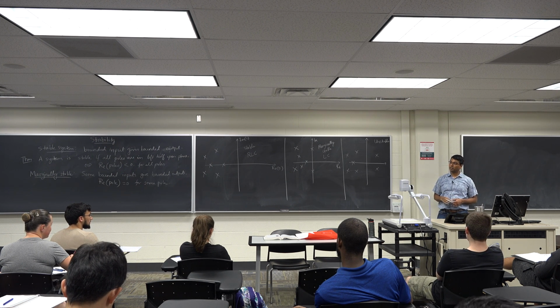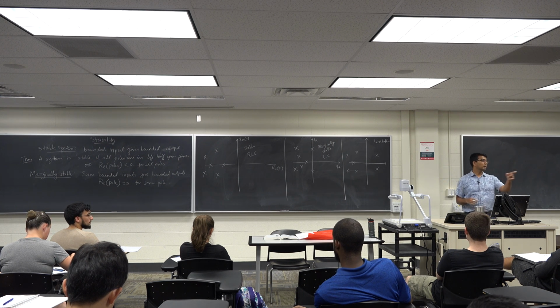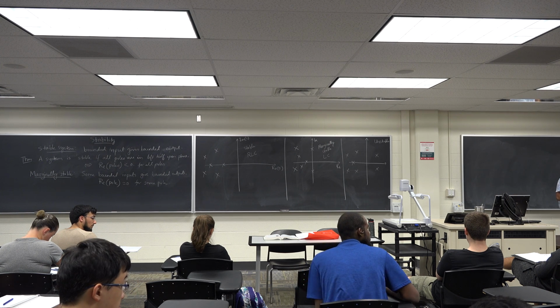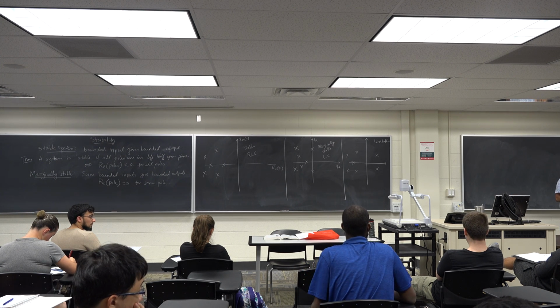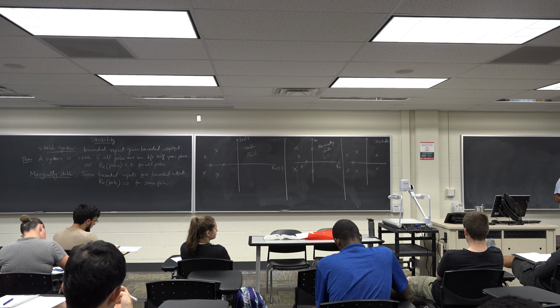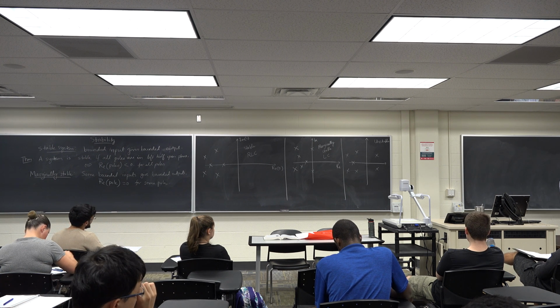Yeah, so those are prominent examples of unstable systems. There was a hand, yeah. When we look at stability, are we only looking at the transfer function? Like when we talk about poles, are we talking about just looking at the transfer function? Yes. So no input at all? No, so stability is the property of a system, not the property of the input.